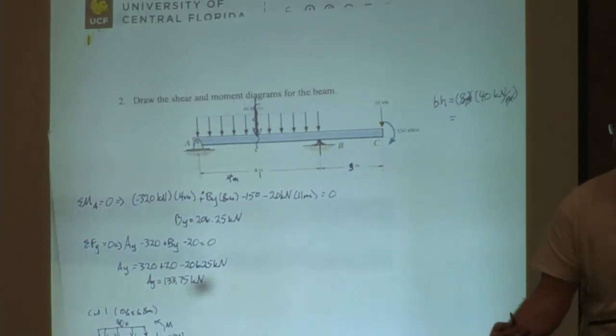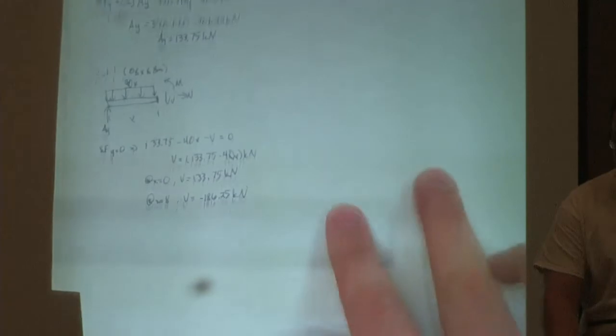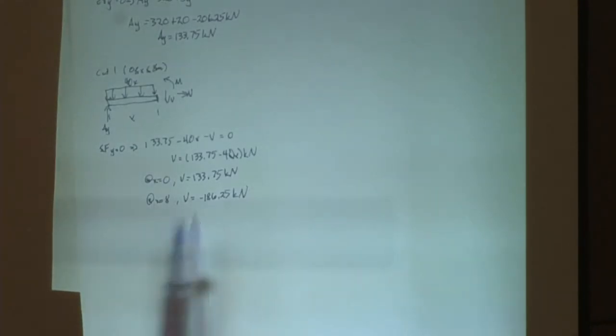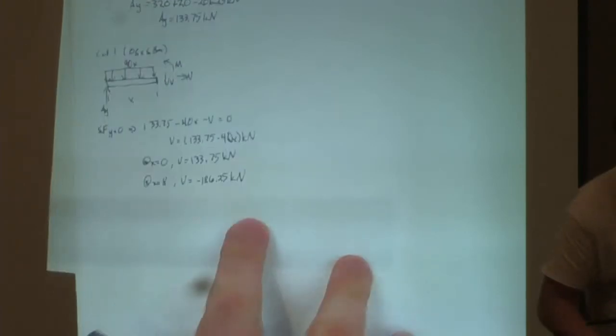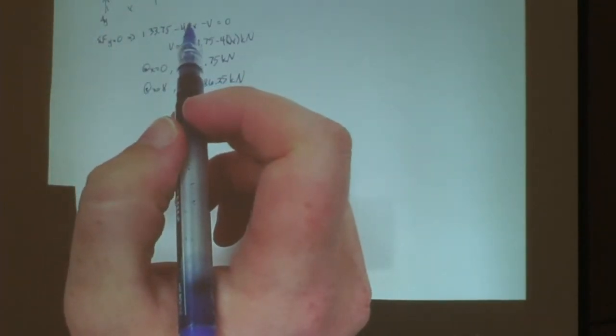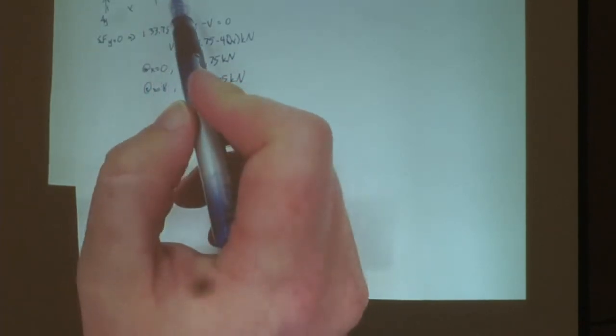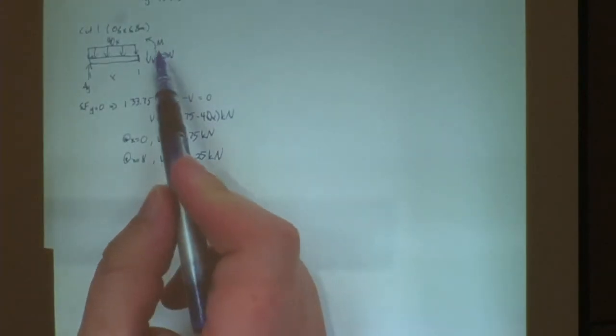So every time there's an additional outside force acting on that beam, you're going to have a different equation for your line. That's why you go through these. You can calculate the shear at any point on that beam with that equation of the line. Any questions? No? All right. From here we're going to go on to moments. And where are we taking our moment? What are we solving for? We're solving for this moment right here, right?